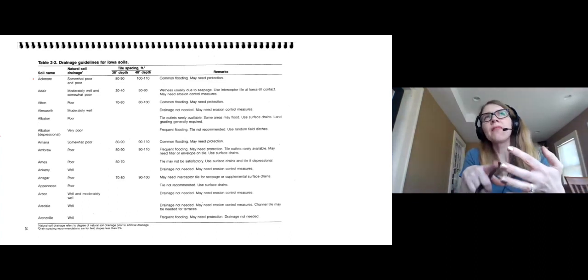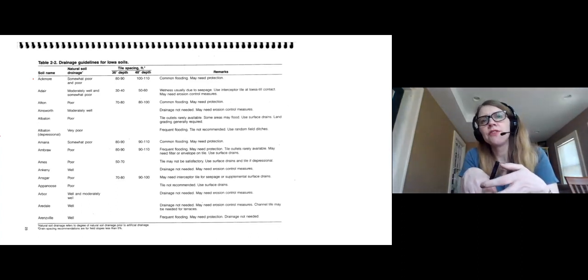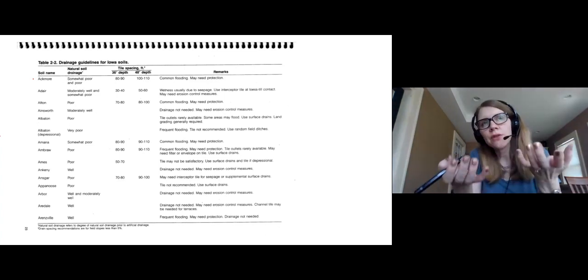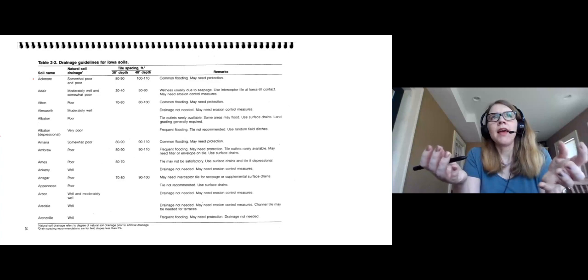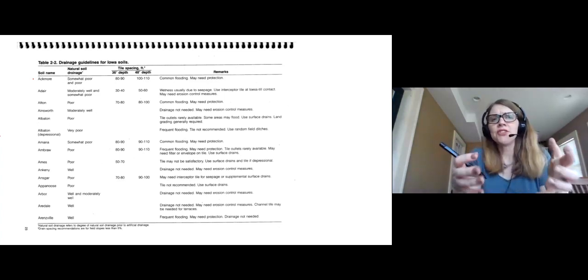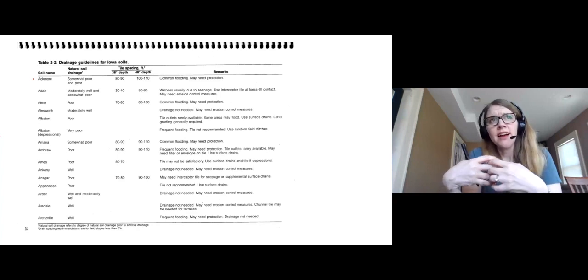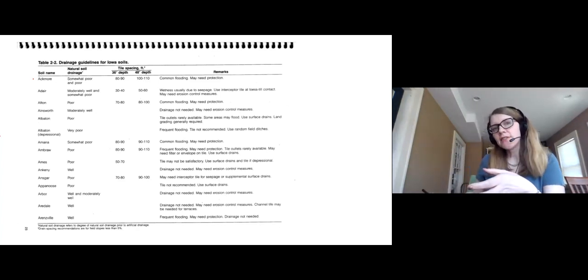Next time, we're going to talk about the relationship between subsurface drainage and water quality, and we'll discuss the idea that shallower drainage drains less water out of the system. And so to the extent that drainage water takes with it nitrate that we might not want to be exporting, if we can reduce the total amount of drainage volume, we can also reduce the total amount of nitrate that's leaving the field.